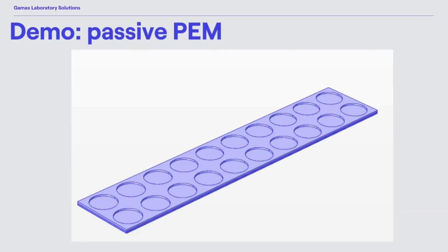And now we can investigate how it looks in COMSOL, how you can set up these passive models. Passive means there is no oxygen flow, so there is no ventilation there. And that's at the cover plate. You can see those little holes. They should be quite large in order to have a good reactant transport to the electrode.